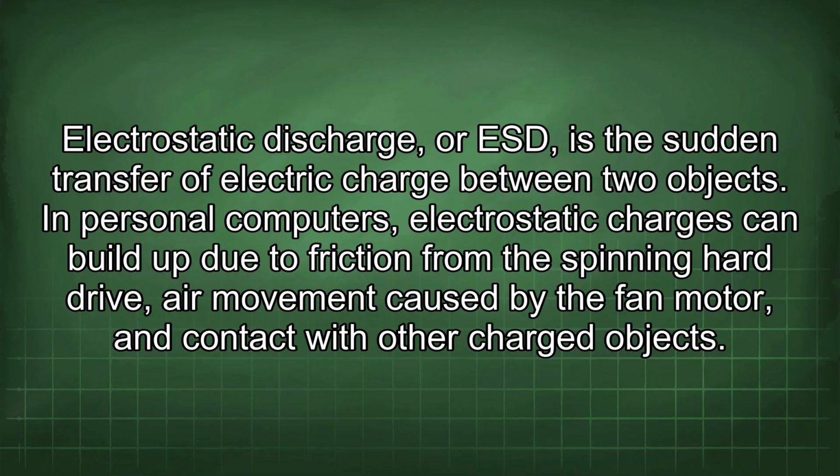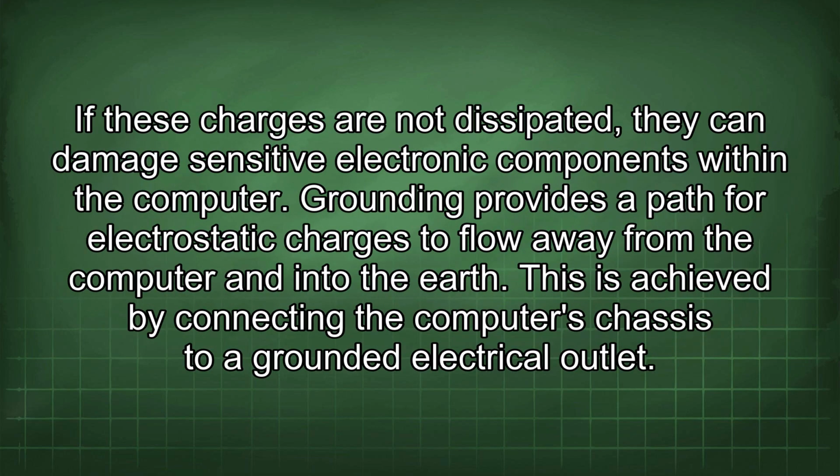Electrostatic discharge, or ESD, is the sudden transfer of electric charge between two objects. In personal computers, electrostatic charges can build up due to friction from the spinning hard drive, air movement caused by the fan motor, or contact with other charged objects. If these charges are not dissipated, they can damage sensitive electronic components within the computer.